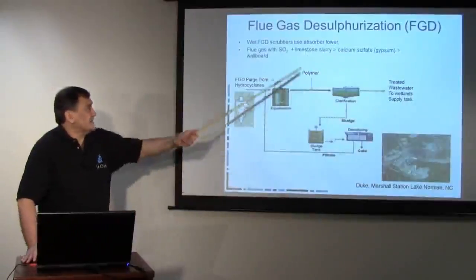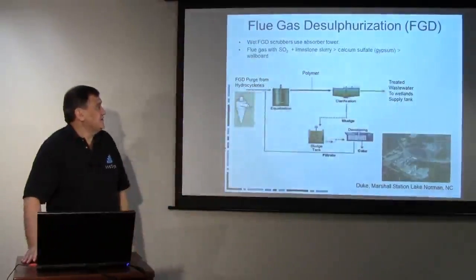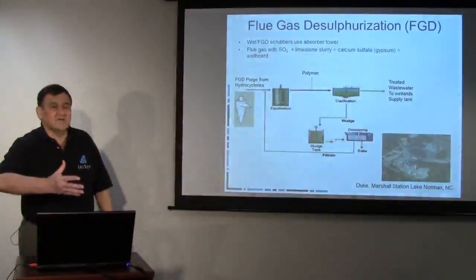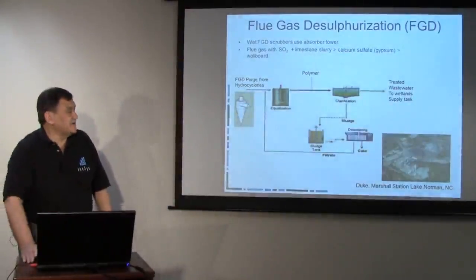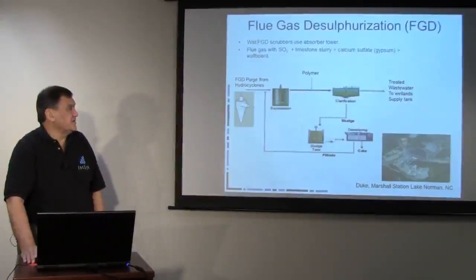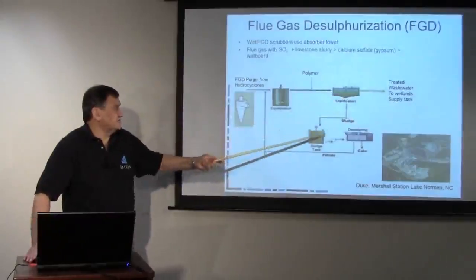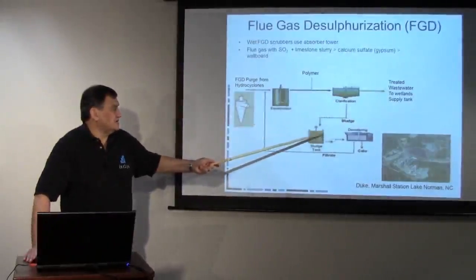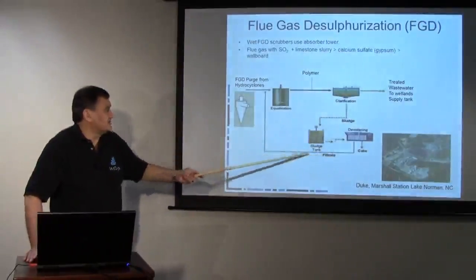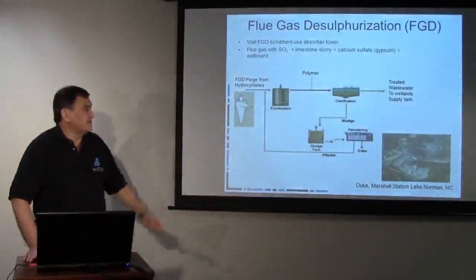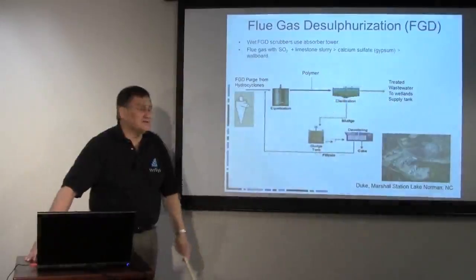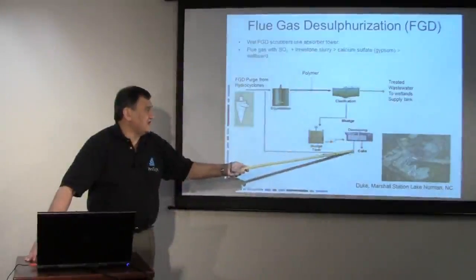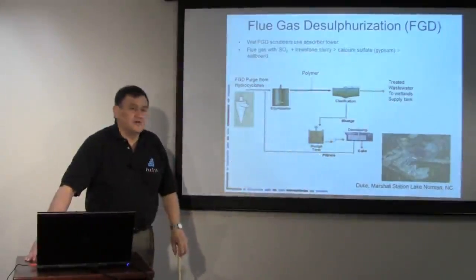But the process, as you mix it with the slurry, it becomes something that you can't dispose of directly, so they actually go through a very complicated chemical processing conversion where they clarify the water, it becomes a sludge, and it goes around the cycle to the point where we get clean water out of here, which is clean enough to put into a wetlands, and we get the dry cake, which we can make wallboard out of.